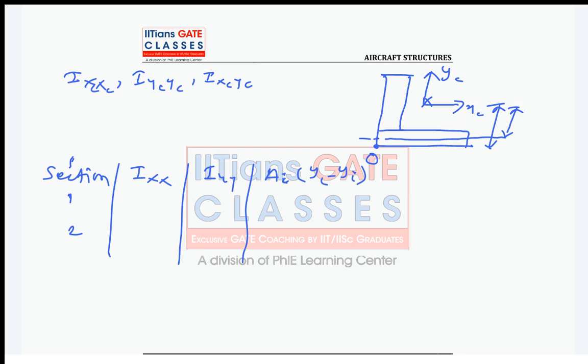Square. Now, guys, one thing you should always remember. Sometimes people write yi minus yc. If you write yi minus yc, then in the next column you have Ai, xc minus xi. Understanding my point, guys? You follow the same sequence. If you are writing yc, then you have to first write xc without any confusion. Otherwise your calculation will be wrong. For which case will the calculation be wrong? Not for the Z section, guys. If you reverse it, your product moment of inertia will be wrong.